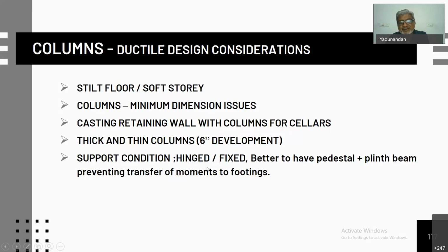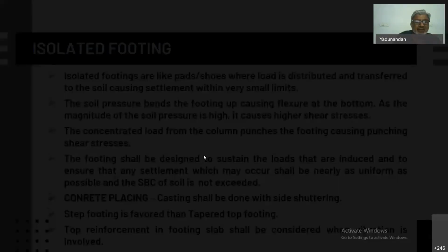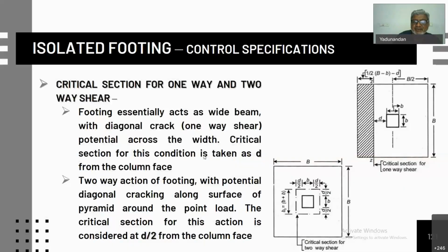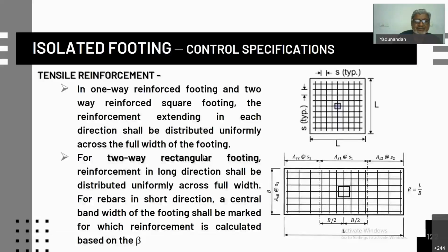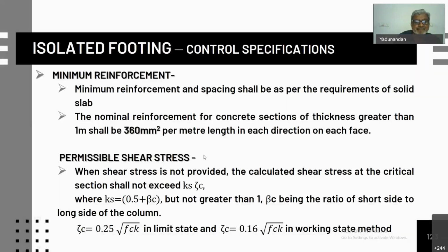Most of the time, for the base support condition, you use a fixed support condition for hard soil and a hinged support condition for soft soil, so the moment is not transferred. Otherwise, you use a network of plinth beam and pedestal so that moments are not transferred to the footings. Footing design I won't concentrate on much, because you have all been introduced to that by the foundation details, and